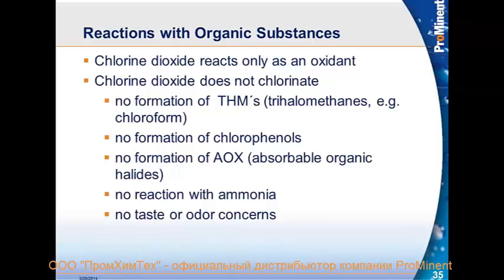And this is important in the wine industry because TCPs, trichlorophenols, trichloroanisols, and tribromoanisols are a problem in the wine industry for cork taint and must and mold. As a result of that, chlorine dioxide does not form any of those. It does not react with ammonia, and it doesn't have any lingering taste or odor concerns if you're using it for such things as washing of fruits or vegetables or washing out containers that wine is going to go into.